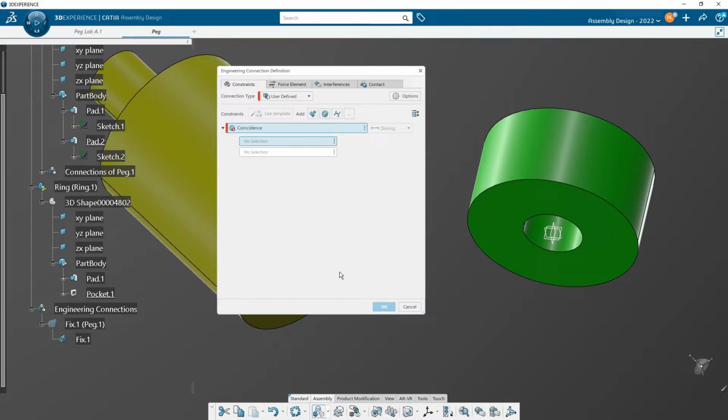So I pick this, and you might be thinking I don't have any lines, but all versions of CATIA have done this: if I have a cylinder, it will automatically find the axial center of it, and that is a line. So for example, on the inside right there, you see that? If I just pick, don't pick the ring, pick the wall, I'm picking that whole cylinder on the inside, and it says, oh, there's a line. If I pick this outside one like this, I'll get the same thing, so it kind of doesn't really matter.